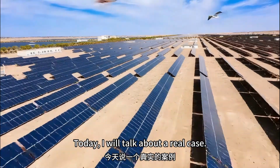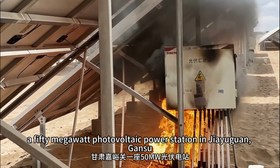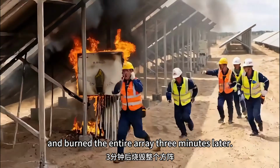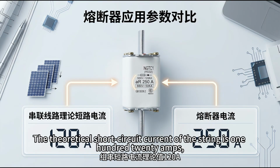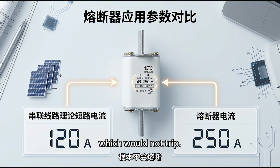Today, I will talk about a real case. In July 2025, at a 50-megawatt photovoltaic power station in Jiuquan, Gansu, the combiner box suddenly smoked and burned the entire array 3 minutes later. The accident investigation found that the theoretical short circuit current of the string is 120 amps, but the fuse was selected at 250 amps, which would not trip.